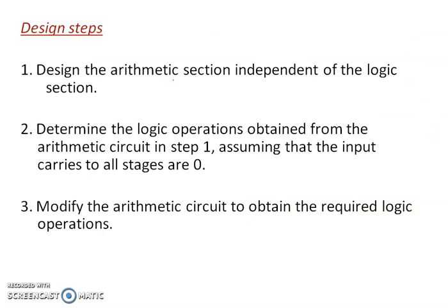So how can it be designed? First, design the arithmetic section independent of the logic section. Then determine the logic operations obtained from the arithmetic circuit in step 1, assuming that the input carries to all stages are 0, and try to implement the logic operations in the arithmetic section.